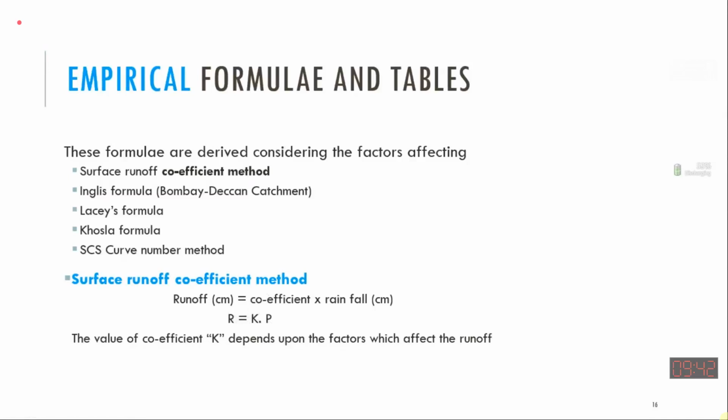In the previous month, so much rainfall occurred, and at this outlet so much runoff occurred. So they got a coefficient relationship between them. They have seen from experience that this catchment behaves in this way, so they have developed coefficients for different catchments. This coefficient depends upon the catchment, its size, its shape, and the weather condition there. These are called the empirical methods.